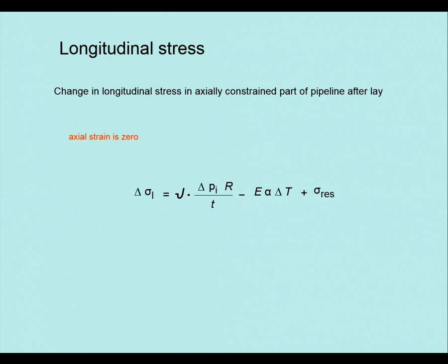But if you've got thermal insulation on it, as we'll see in a little while, the temperature of the steel is retained much more closely to the internal temperature of the fluid. So you have to be very careful using that, because theoretically, if it's got a perfect insulator on it, your temperature on the outside of it is the same as your seawater.